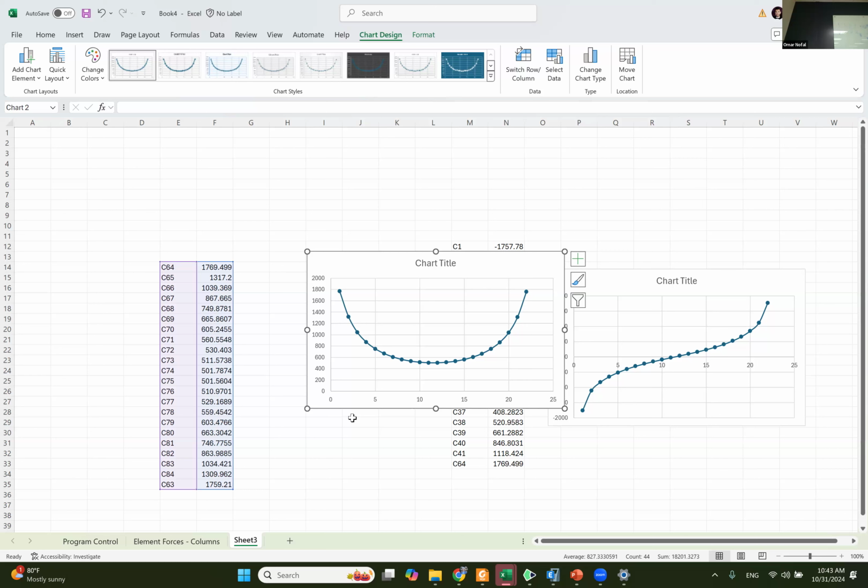Okay, so I want you to do this for every model, maybe plot 3 or 4 of them at different story heights. Do them for all models, and then I want one curve at the end after we finish the 12. Plot maybe all the curves at the basis story for all the models, and plot all the curves for the story number 10 for all the models, and see how the shear lag is changing. Okay, for both the side and the front. All right, and I told you about the bonus, how we do it.